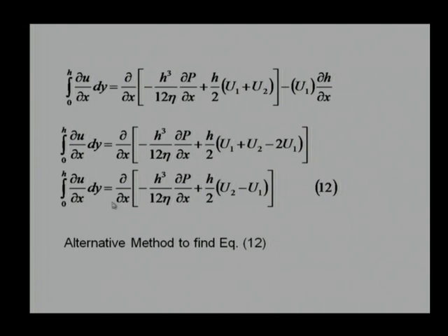So, still we need to differentiate it, but the pressure gradient term remains the same and the velocity term is getting changed due to this addition or subtraction. There is a relative velocity and that is a negative relative velocity. We say in this case it is u2 minus u1. We know u1 is greater than u2, so both will turn out to be negative, and the negative can be taken out.